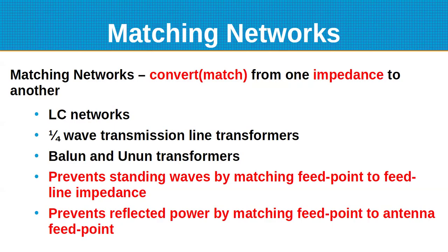And normally the inductor will have taps on it, and you'll have a switch that you can select which tap or how much inductance. And then you have to rotate the variable capacitors to change the amount of capacitance. And you go through that process twiddling all 3 of those knobs to get the best match.